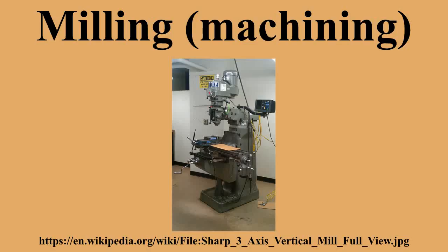Ram-type mill: this can refer to any mill that has a cutting head mounted on a sliding ram. The spindle can be oriented either vertically or horizontally. In practice, most mills with rams also involve swiveling ability, whether or not it is called turret mounting. The Bridgeport configuration can be classified as a vertical head ram-type mill.